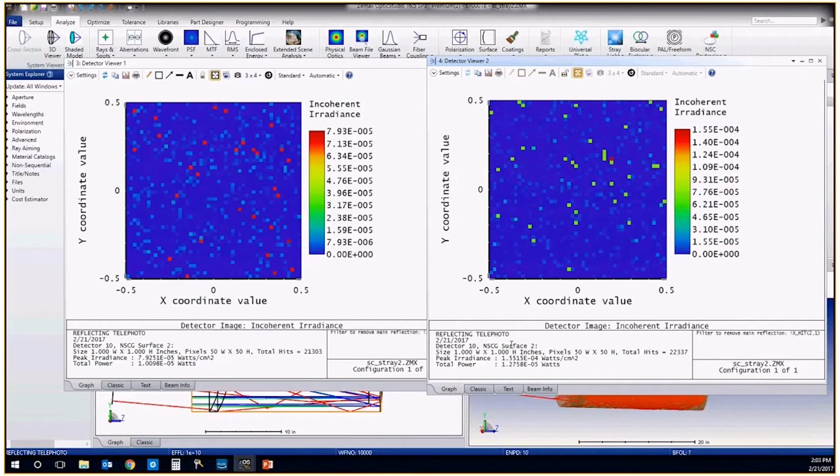The powdered black steel, because it's an IES model, does have some corresponding energy information within it. So in other words, we have TIS values, which are total integrated scatter values. So if we know that we have 1 unit of input power, we measure how much is output into the scattering, whereas the Gaussian model is relying solely on that coating in order to provide that information.